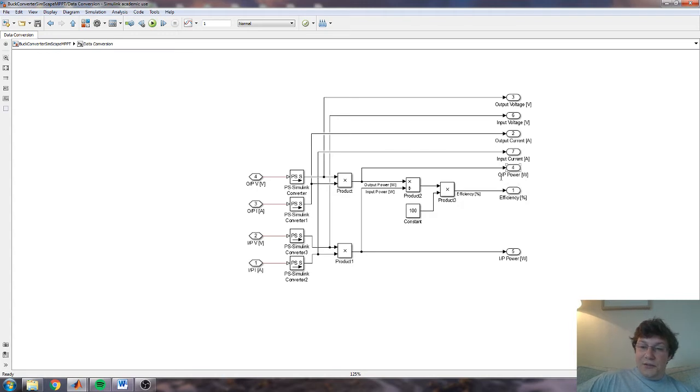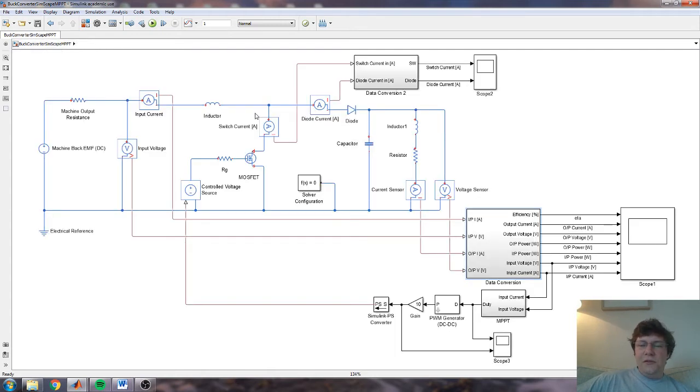But there is stored energy in the system, especially under transient conditions, when it's starting up, or when you step the load or something like that. You can get some unusual answers. But from a steady state perspective, when the energy in per cycle and the energy out per cycle are reasonably constant, it works well enough. If you wanted something a bit better, you could do it on integrated energy transferred. It would be a slightly better way.